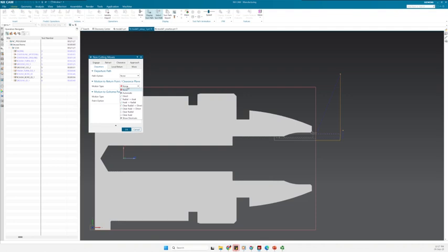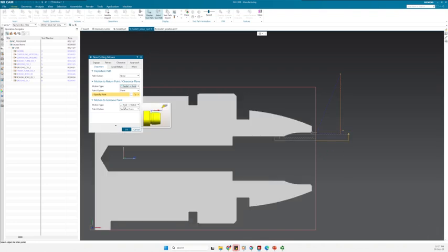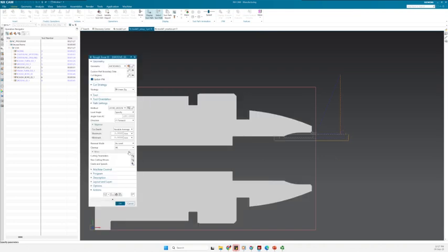Then we can go to the motion start points. Then after that, I can define again radial to axial. And then specifying points, I will specify it here, and then optional points. For this one, I can put the points and define another point here, and then click.